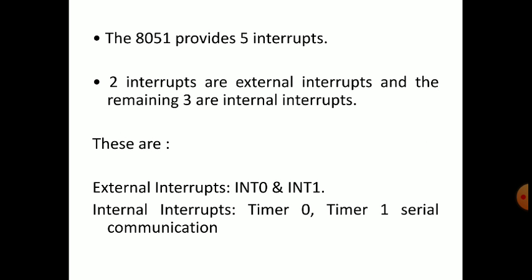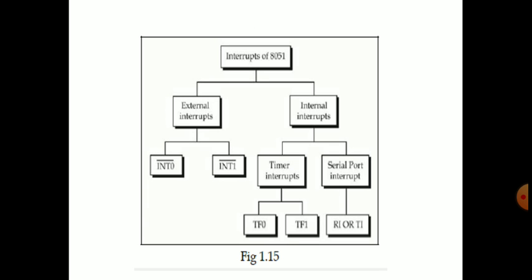So this is the part. 8051 provides 5 interrupts. 2 interrupts are external and the remaining 3 are internal interrupts. External are INT0 and INT1. Internal are timer 0, timer 1 and serial communication.